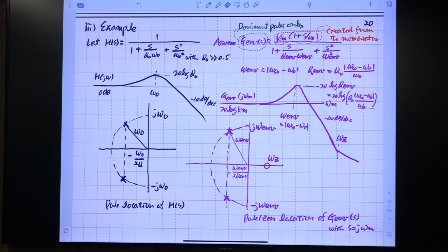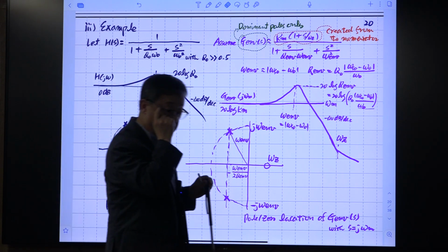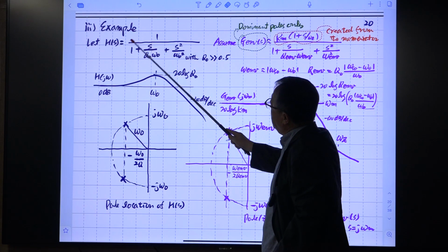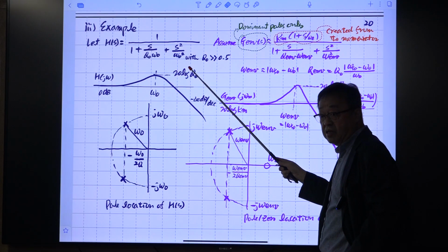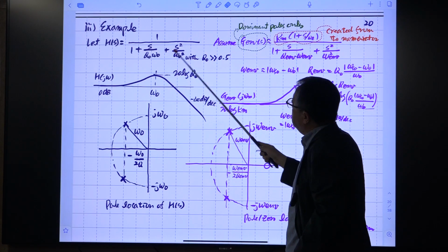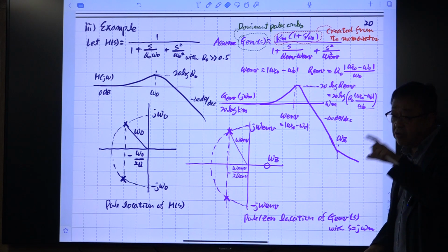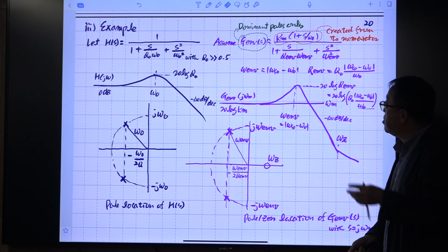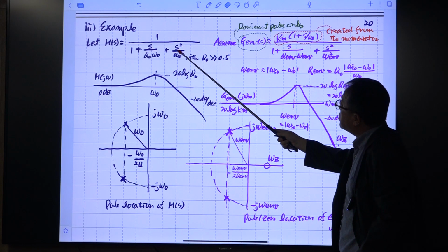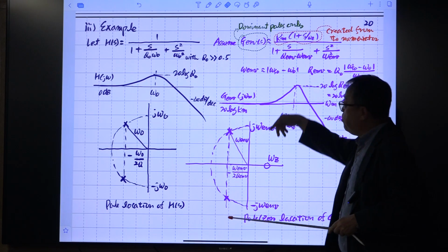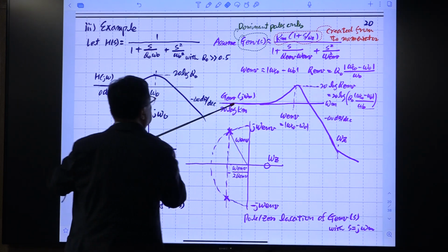Right. So suppose we have a simple LC type, simple resonant tank circuit. Then the transfer function of the tank circuit is something like this. This is the transfer function of a parallel loaded series resonant tank. The tank circuit we were playing with in the previous lecture is exactly this form. Then maybe we need to go through the process, but the result will be this one.